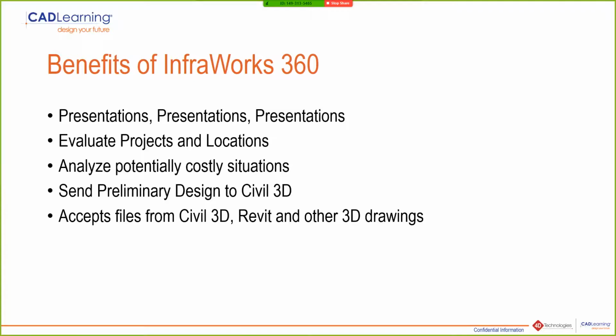You can't do that with Civil 3D. You have to send the surveyor out there, bring the survey back in, and then put it in. It's going to take a day, maybe 2. And it'll take you about half an hour more, at least, to get the survey in there, and another hour or so to make the surface, or longer.